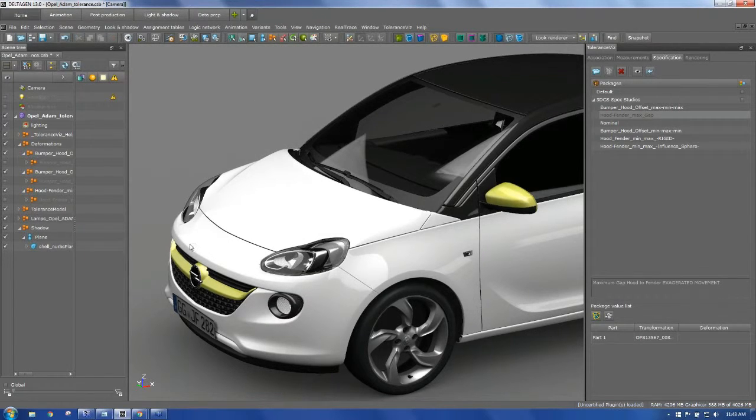Regularly use it. Now, my materials in 3DCS, if I've named them the same as they are in DeltaGen, will they convert automatically? No, because you have to initiate that tie of saying this material is associated with this DeltaGen material. Gotcha. So even if you name it the exact DeltaGen name for that white paint, it still doesn't know that your paint is associated with DeltaGen's white paint. So you just have to build that bridge together. Once it's done, it's a huge time saver.